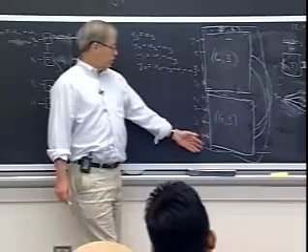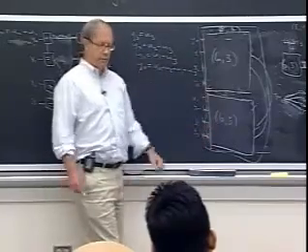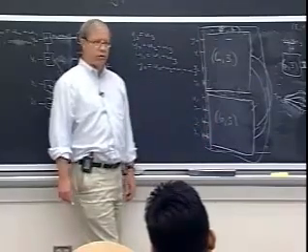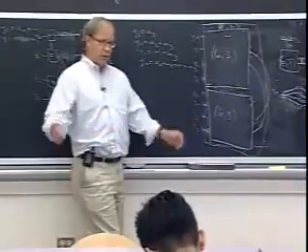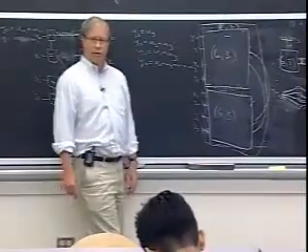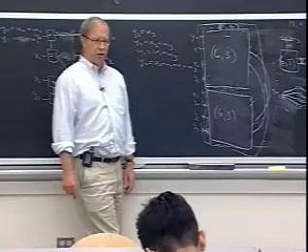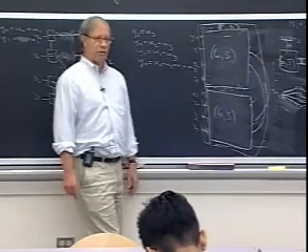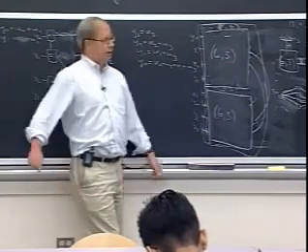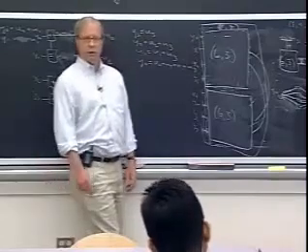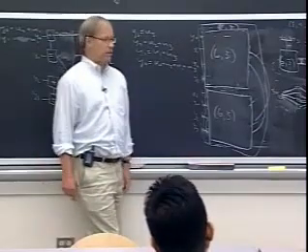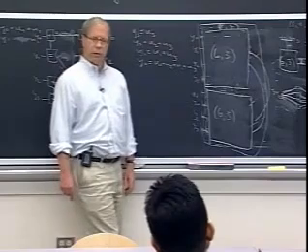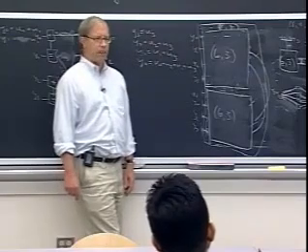For instance, in turbo codes, we'll make it up out of several convolutional codes. There'll be several trellises. We'll do BCJR decoding of one trellis. That'll give us a bunch of a posteriori probabilities about the bits that are involved in that trellis. Then we'll pass them back to some other trellis decoder that's decoding an apparently different trellis but involving some of the same bits.